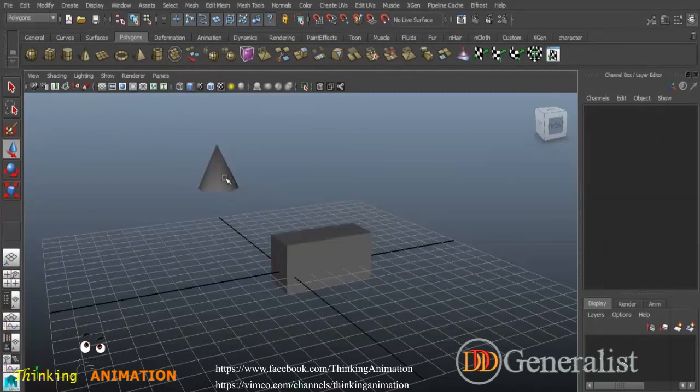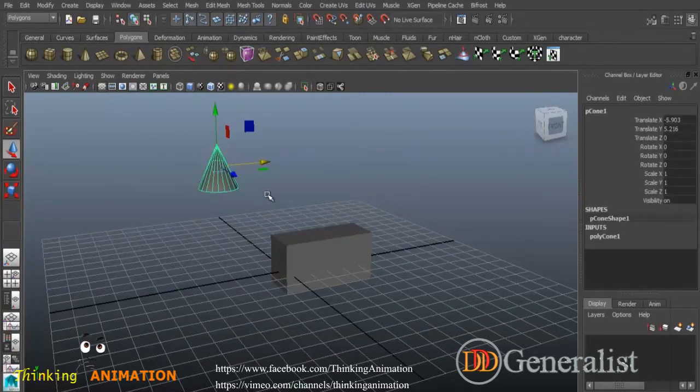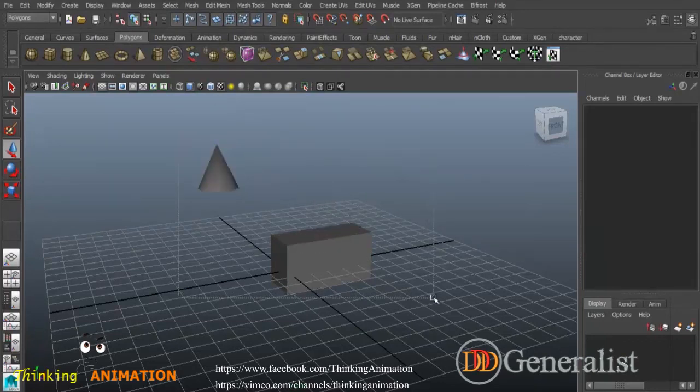So if you have multiple children in your shot, you have to select all of them first, then holding down Shift, you press Parent at the end, meaning the last object selected will become the parent object, and all other objects selected before that will be children of it. So this is another important option, and you should know about it. This way you can easily manipulate things inside your application, your tools.